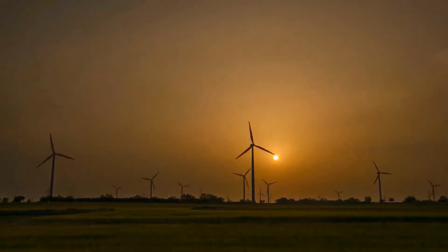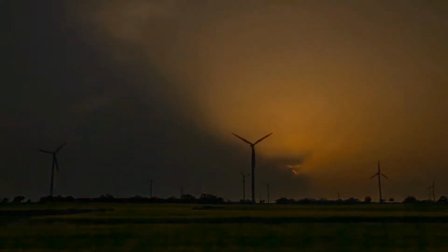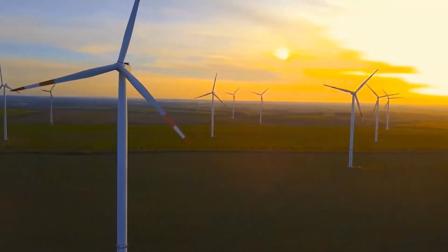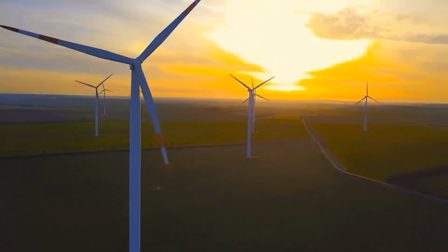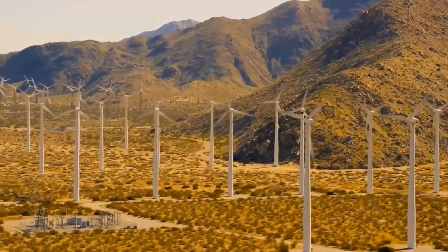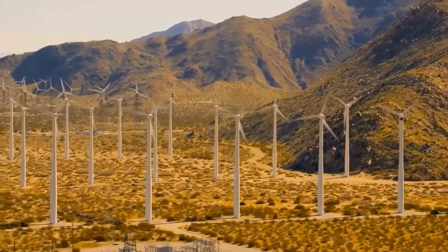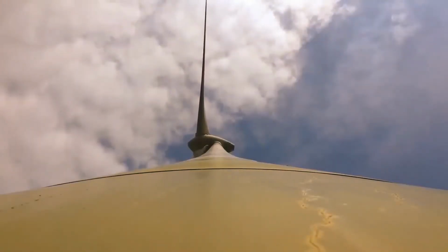This destruction has been created due to a specific force, and this value of force is created because of a specific relative velocity of flow that is called the flutter phenomenon, and the fluid speed of destruction is called flutter speed. Recognizing the flutter speed, we can ensure the safety of structure under aerodynamic forces. In structures such as turbines, flutter velocity is a velocity which must not be reached by a turbine under any circumstances, and not considering the flutter phenomenon in our initial design became our downfall.